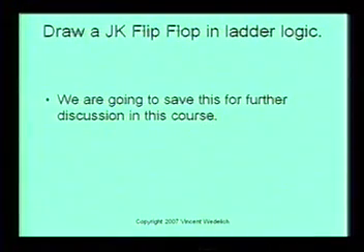Then I asked you to draw a JK flip-flop in RSLogix. Later in this course, we're actually going to do that. We're going to take another type of JK flip-flop, convert it into ANDs and ORs or NANDs or whatever, and then take that information and convert it directly into RSLogix.